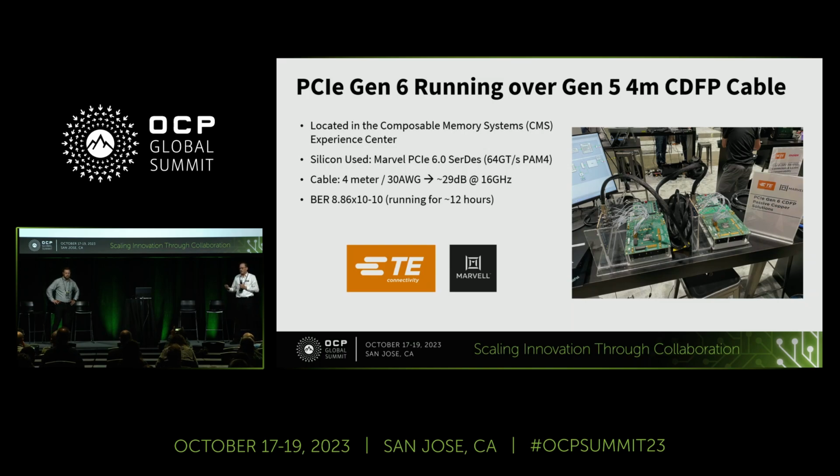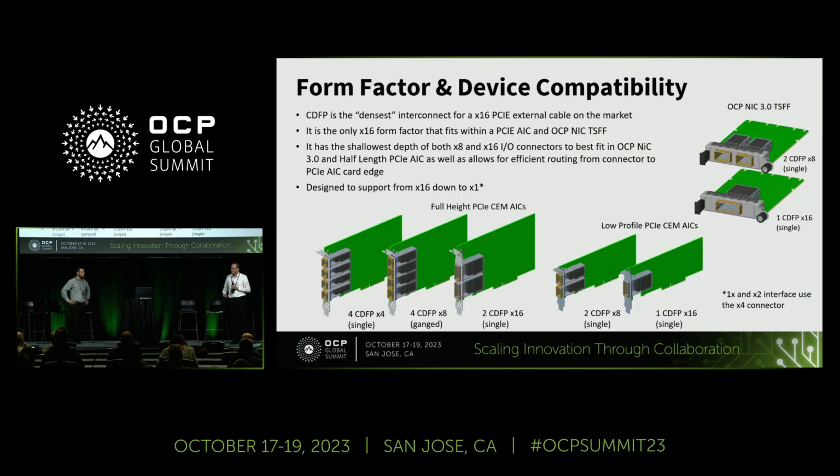So your mileage will vary. If you're architecting your system with this in mind, you can get a lot more for your application going with just a strictly passive copper cable, which, as we heard Andy Bechtolsheim mention earlier, is about a 10x cost penalty to go to optics over passive copper. When you go linear, you're saving maybe 30% or so, and so people are going to use passive copper as long as they can, and we can enable that with CDFP.